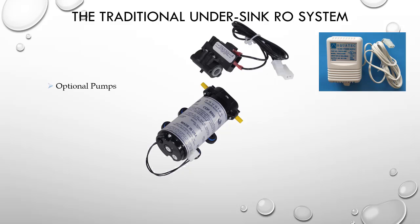That means if you had 500 TDS in the raw water, it will take 5 psi to just start the process of reverse osmosis. However, what is not taken into consideration with this equation is pressure lost or needed to push household water through all of the cartridges, the fittings, and overcome the storage tank back pressure.